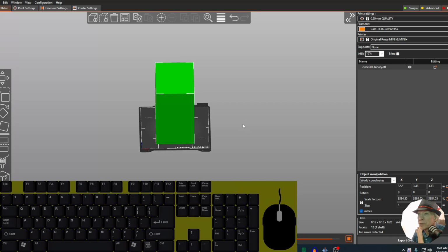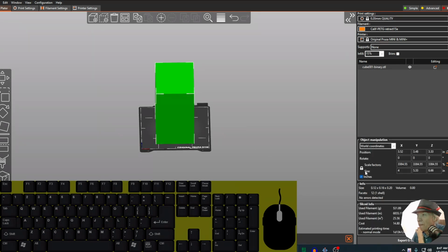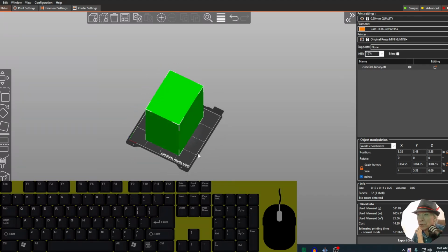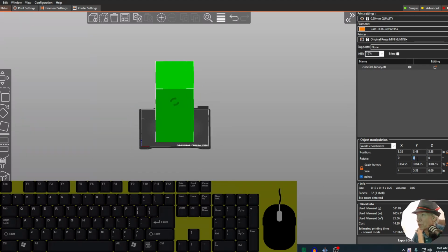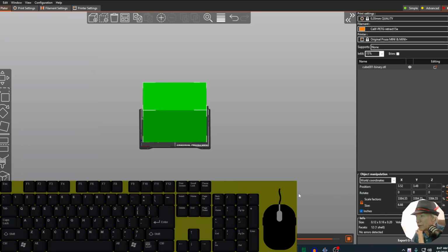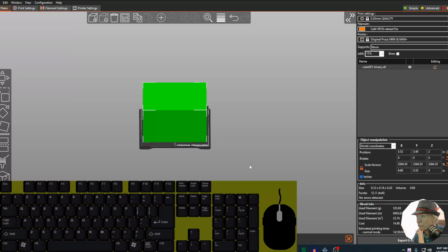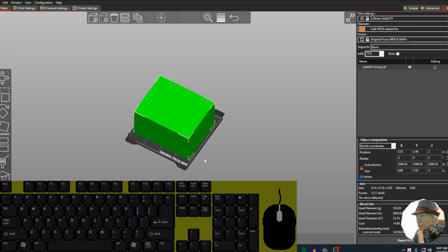Now notice we can print this a couple different ways. Okay, we could rotate this on the Y. So our print time here is 1 day, 3 hours. Okay, so it's taken a day to print that. That's incredible. If we rotate this 90 degrees and print it that way, it's still generating G-code. Wow. So it's a little bit faster. It's still 1 day and 2 hours.